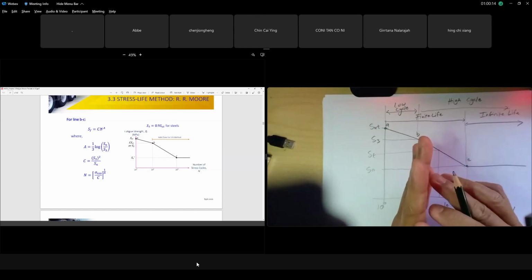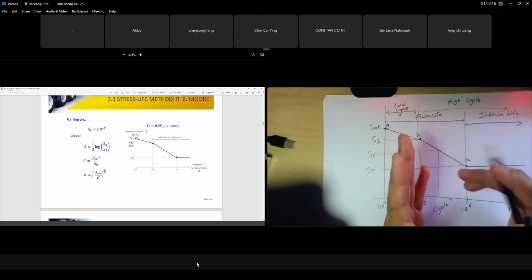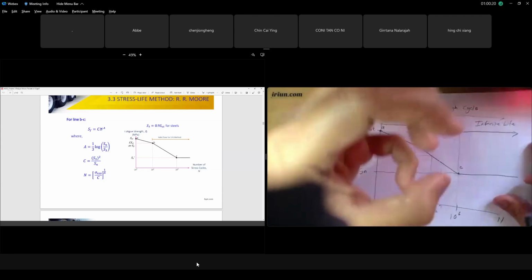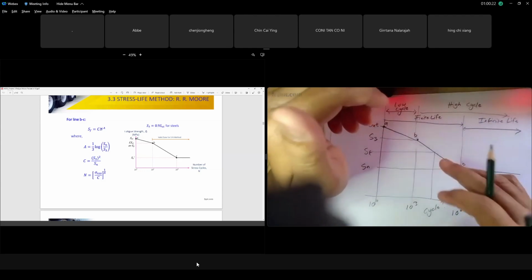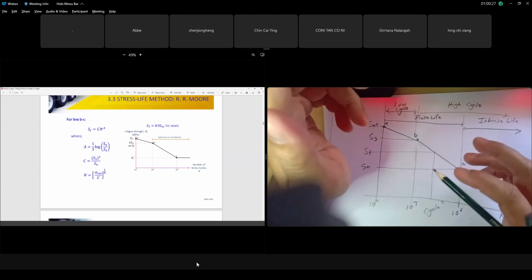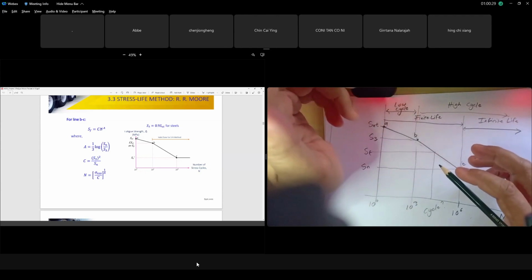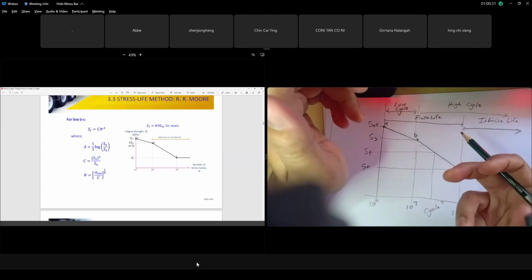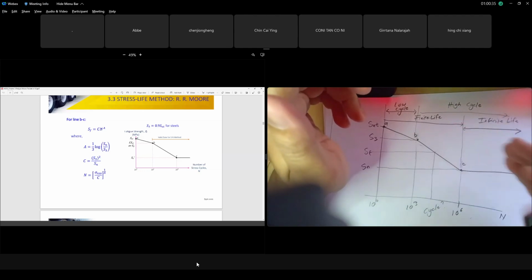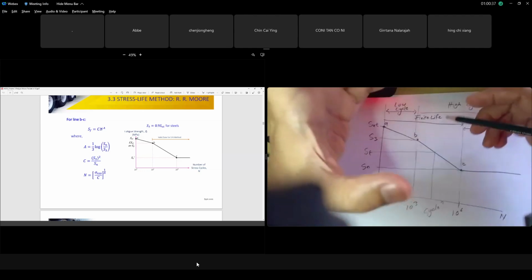You combine the moment MSY squared plus the moment MSZ squared at point B, since B is the greatest moment, summation, square root. Then you calculate the bending stress, sigma equals 32 times the moment at point B over pi d cubed. That's your bending stress, the denominator. Then you also find sigma E, which is sigma x squared plus 3 tau x squared, if you have torsional stress, combining the torsional stress.